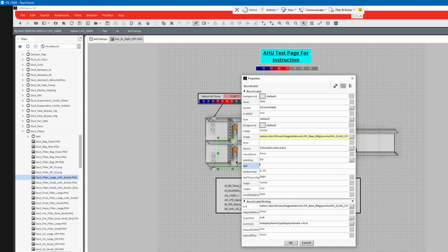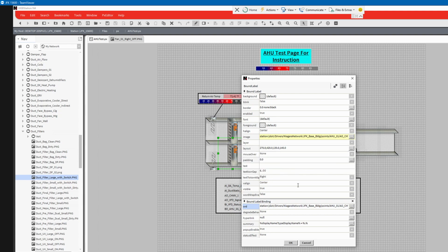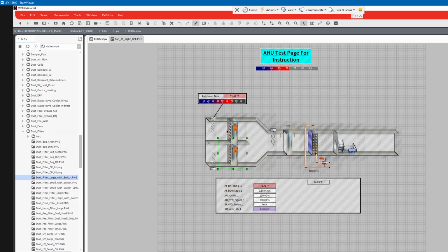Now you can change your ord, and you can go find your outside air damper, your return air damper, whatever damper it is that you have going on, and start showing it here. What we've also done is, let's say our outside air is on a fan and being fed by the fan. A lot of times we'll move these dampers a little bit further back, and we'll put a fan motor right here, showing that the outside air has a fan, and we'll put the status in there.